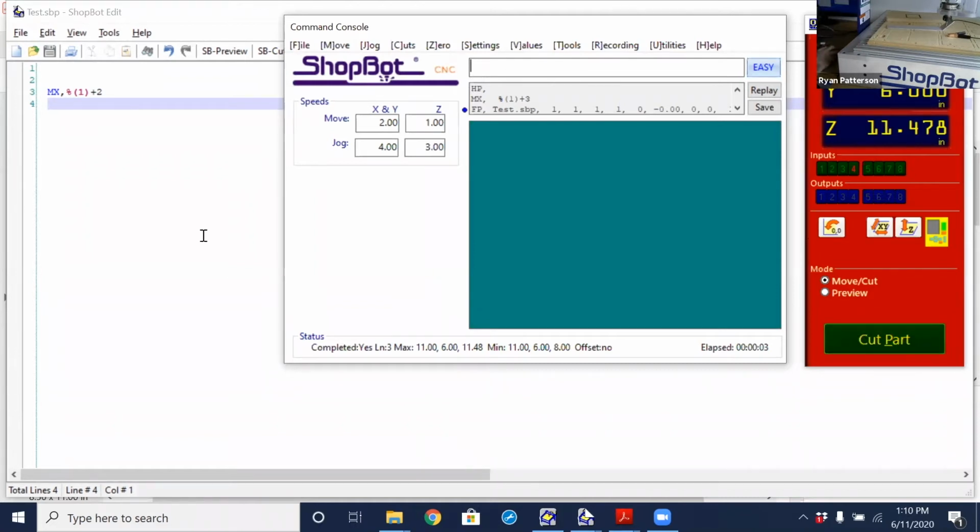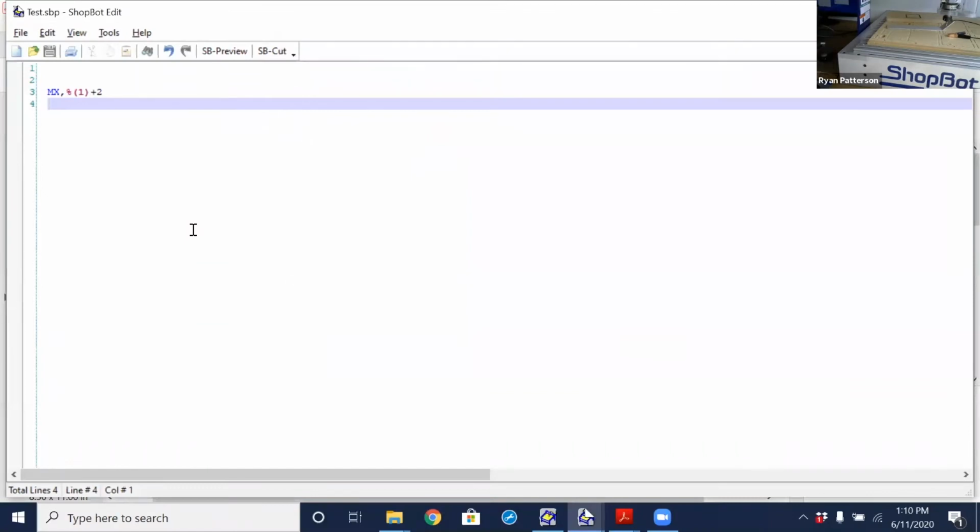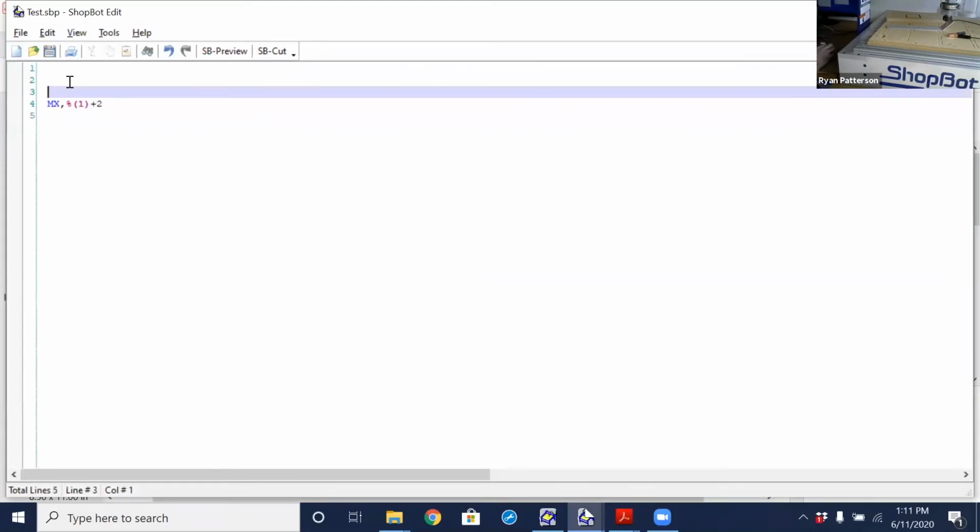So now we're going to get into more of programming, and I hate to throw out the first programming statement off the bat because it's a little harder to understand maybe, but it is what is called an on input statement. So on our line here, what this is saying is we are going from on input 1. So when switch number 1 turns on, we're going to go to contact 1. So to explain what contact 1 is, that's a label within the file.